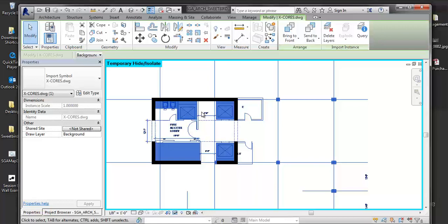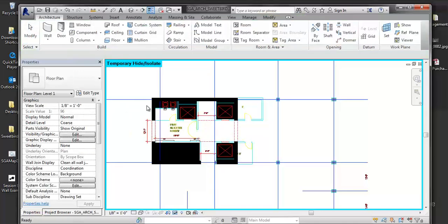So it's one thing to keep in mind when you're doing Revit content from a CAD plan. You really only need a single line for that room boundary. You don't need to draw out the wall lines if you are using CAD for that particular procedure. And then you would punch the openings instead. Exactly. Then we punch the openings, because we don't want to have to build out separate walls for the headers. We want to have that as continuous as possible.